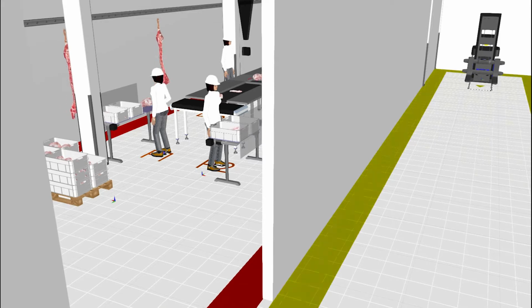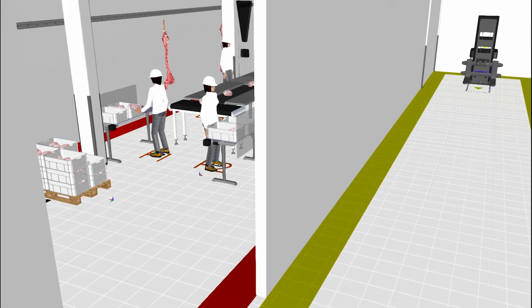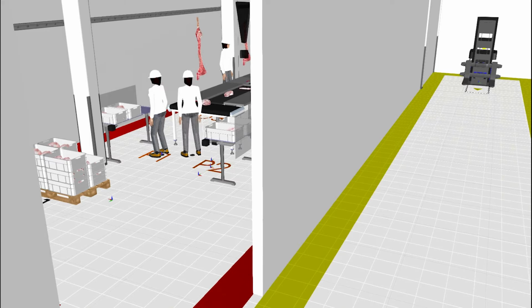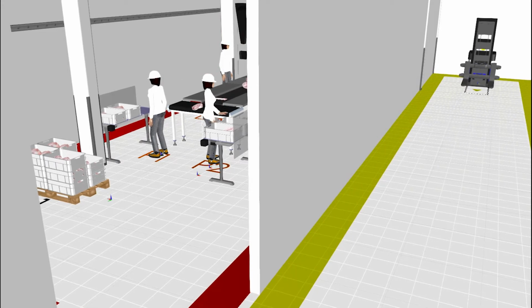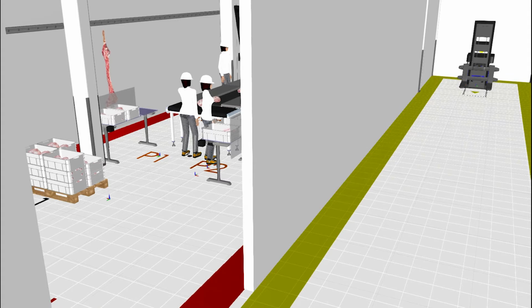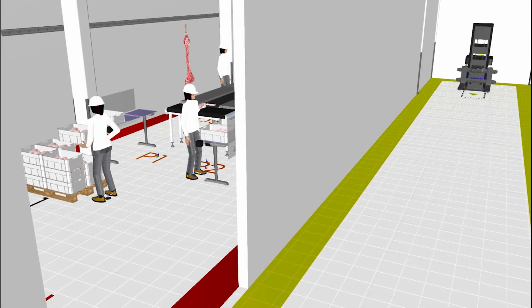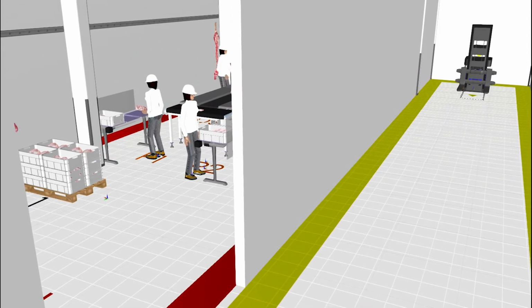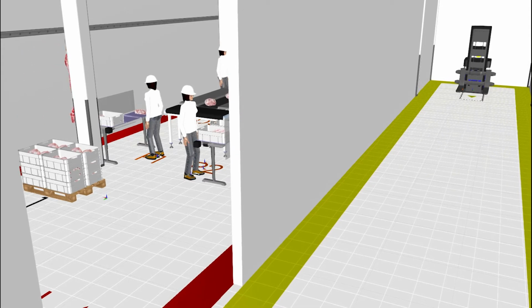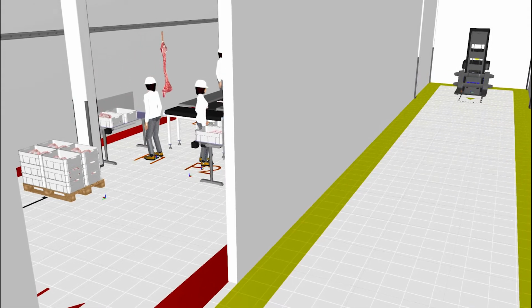In all of these transfer operations with the forklift AGV, a virtual guide path with laser navigation is proposed. The proposed guide path assumes basically 2 service functions, pick up and drop off, with several different positions. AGV stops could be controlled automatically from ERP, or manually according to information from the operator using a push-button call box. Towing capacity is up to 1,000 kilograms.